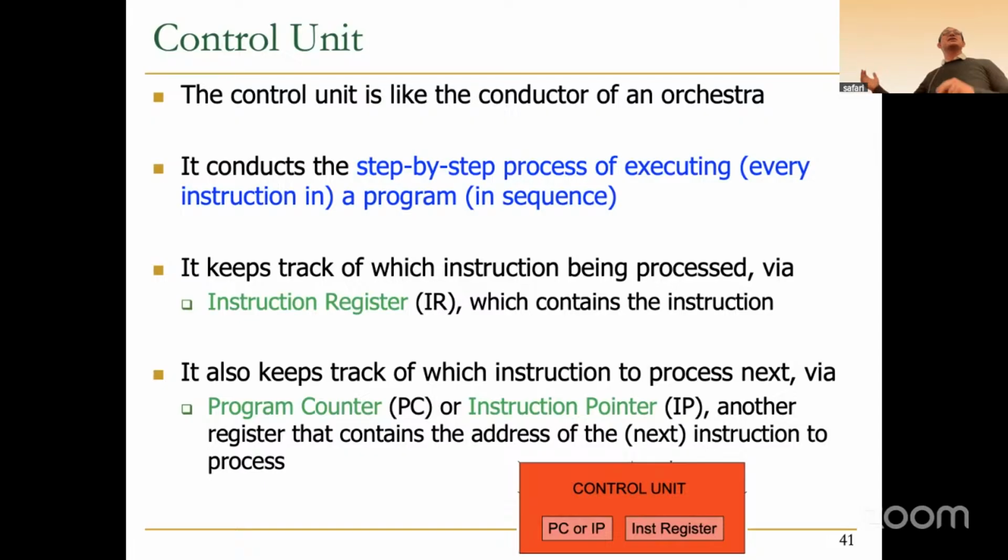And the instruction register provides the storage for the bits of the instruction that specify what the computer should do. So the program counter is the address to fetch the next instruction from. The instruction register is the data value of the instruction. Does that make sense?